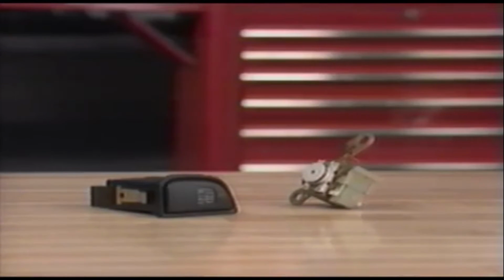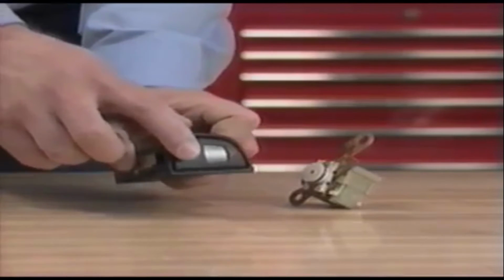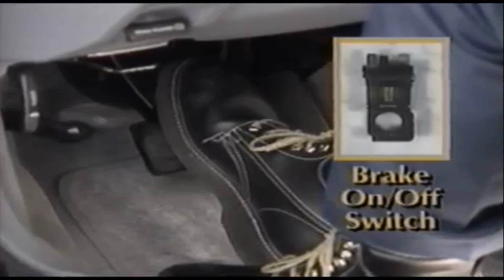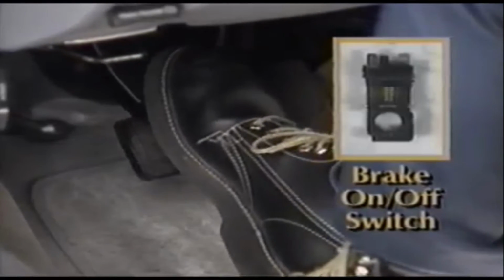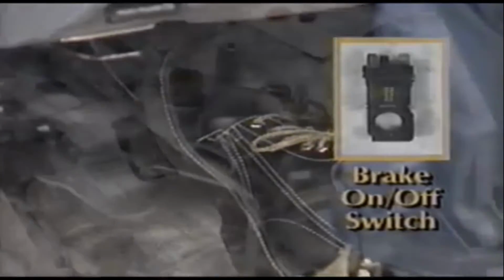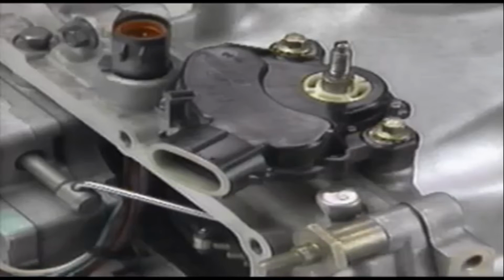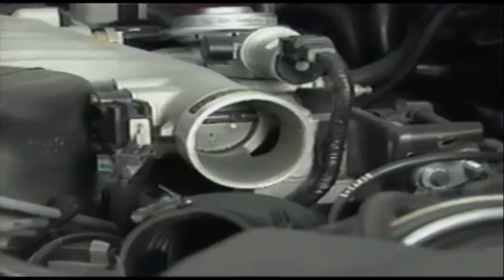Controlling devices used in electrical circuits include switches and solenoids. Switches are simply the on-off controls in electrical circuits. There are many types of mechanical switches that depend on the action of a component to complete a circuit. Brake lamp switches and the manual lever position sensor are examples of this type. Sensors allow variable control of voltage or resistance.